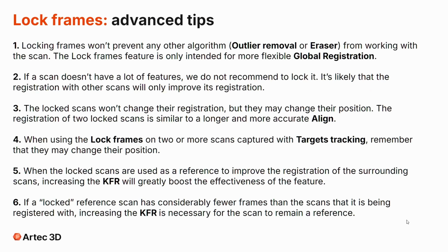To conclude this section, let's go over a few advanced tips to keep in mind. First, remember that log frames is specifically designed for global registration. It won't stop other tools like outlier removal or the eraser from doing their job. Second, avoid locking scans that are feature poor. These scans actually need global registration to improve their internal alignment.